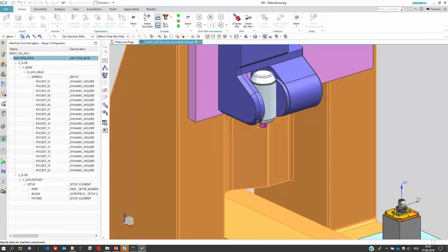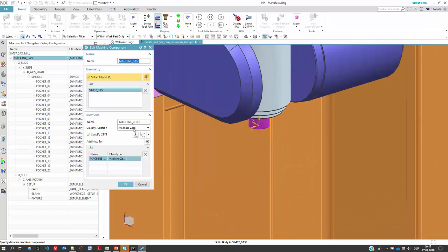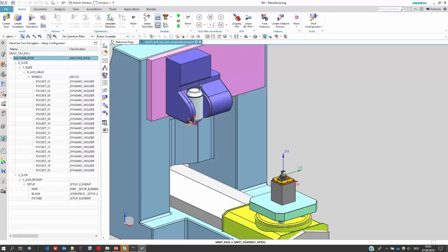that when all axis values are zero, the tool tip, the tool mounting junction must match the machine zero junction. If this is not the case, for example, the machine is assembled in this way here, and the machine 0 position is maybe in the middle of the table, you have to tell the system the offset between the assembled position here from the tool mount to this position on the table.